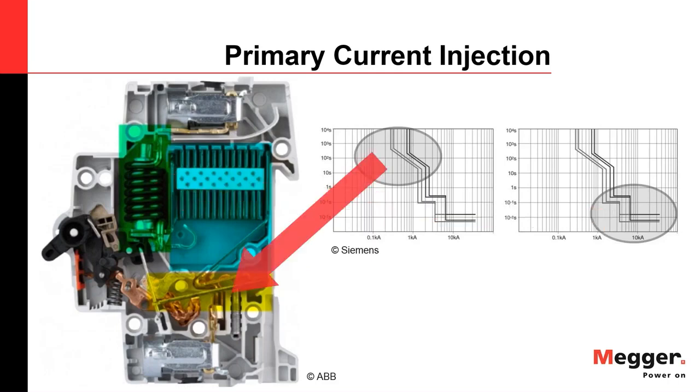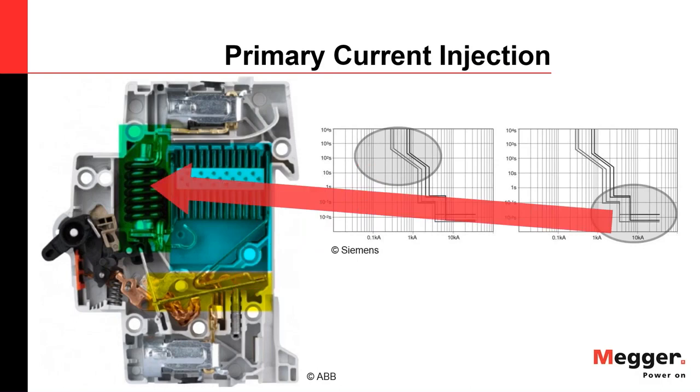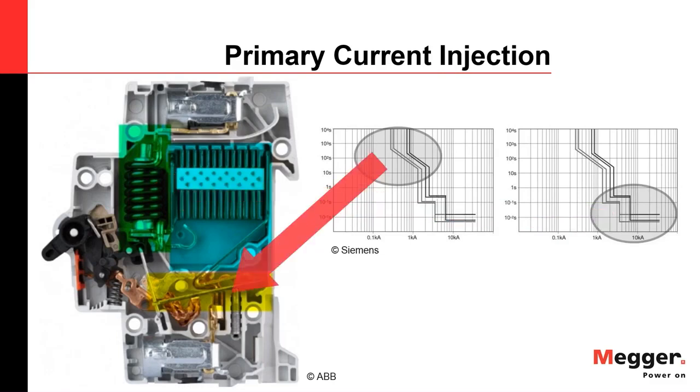So you see the long time, that is the bimetal portion, fairly low overcurrents for a long time before that element trips, and no time delay, high currents picked up with the CT and leading to an immediate operation of the circuit breaker. There are actually circuit breakers that can be in this portion of the curve for minutes, 10 minutes, 15 minutes. So it's not always seconds.